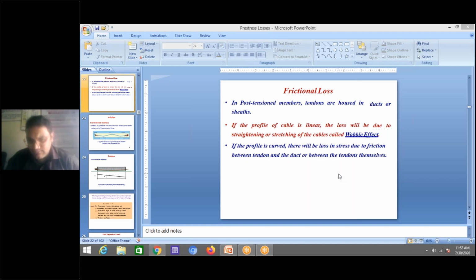Sir, the axial pre-stressing chapter once. What do you mean by axial pre-stressing? See, all longitudinal pre-stressing will be axial pre-stressing. Let us take a beam and put a strand inside. Consider a pretension case: you apply force through its axis, so the force is transferred through the center of the section. That force is an axial pre-stressing force.